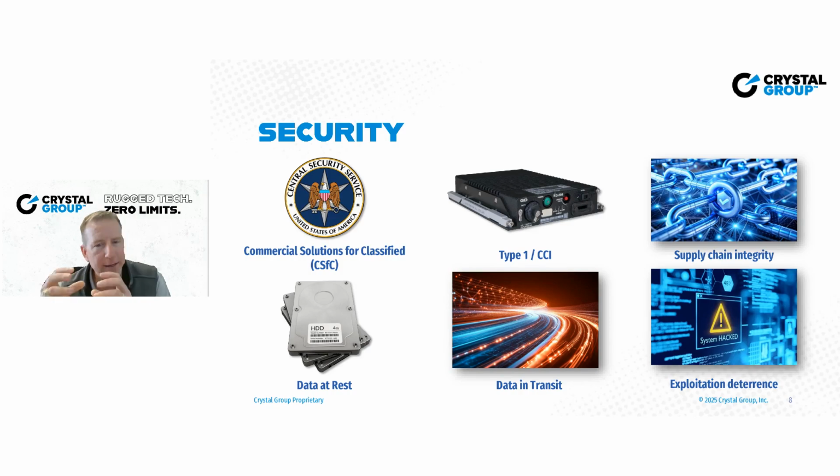And so you got to think and be very clear and aligned with the customers, the users, and the designers of what are we putting security on and what type of security are we talking about? Because that will ultimately drive significant impacts into the speed, because anytime you have encryption, you generally are going to take a hit in bandwidth and processor capacity, or basically you're going to erode some of your processor capacity. Additionally, you got to find room for this stuff, whether it's logical if you have software, whether it's hardware if you're using like a type 1 encryption unit, for example.